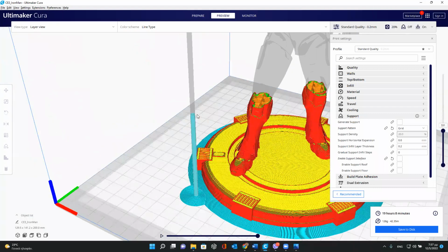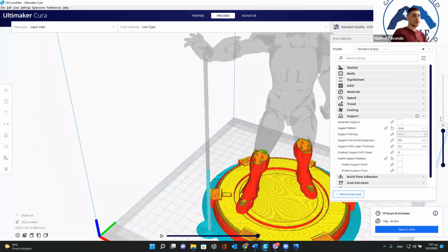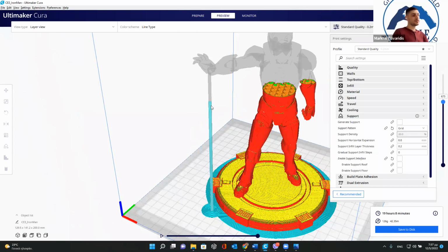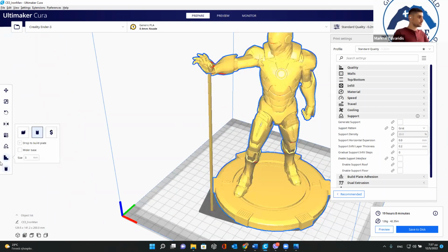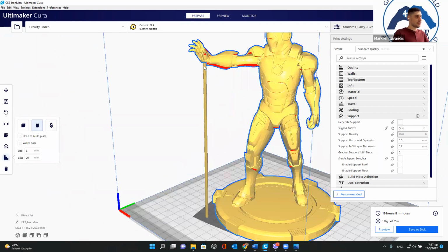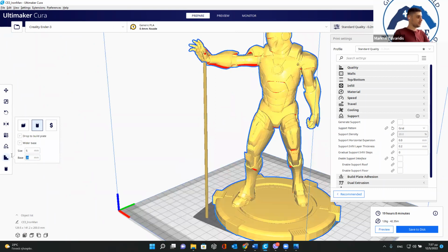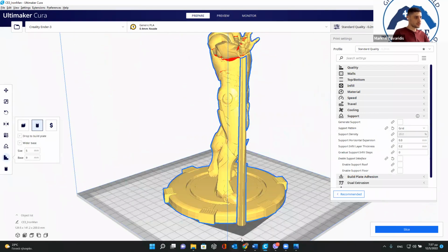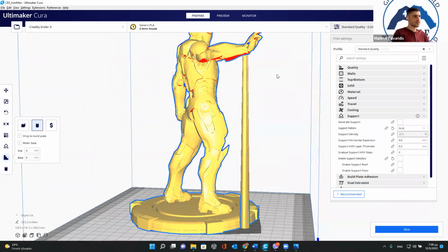But if you touch this, for example, if there is a small failure, let's say on your printer, it goes fast here and it touches the support while it prints it, it may fall. It may move. So what you need to do is actually use the wider base. So this time you have the size of 5 and the base of 8 or 9. And you see that this way it's actually safe. It's obvious that it's safer to print on top of itself.